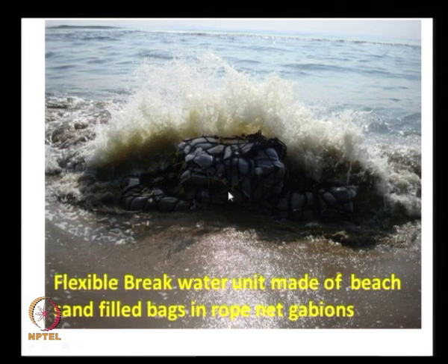And here we see one innovative application of the geosynthetics for coastal erosion protection. Here this breakwater was made entirely by using the beach sand. The beach sand was filled in these geotextile bags, which are in turn placed inside a rope net gabion, and everything is tied together to form the breakwater units.